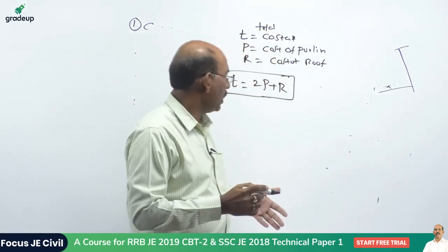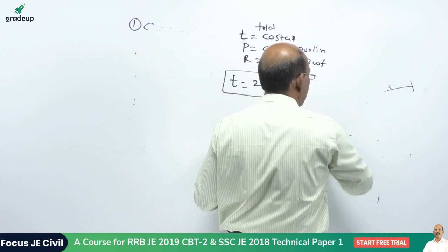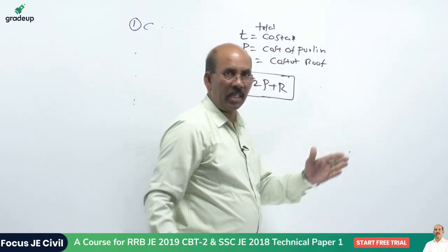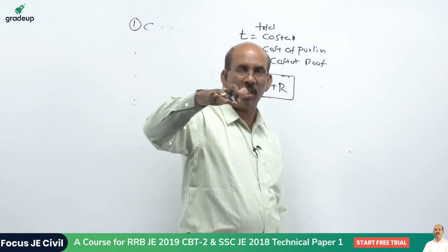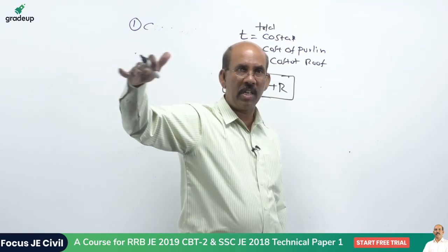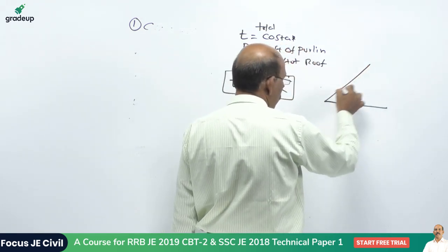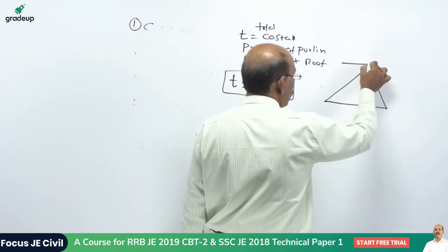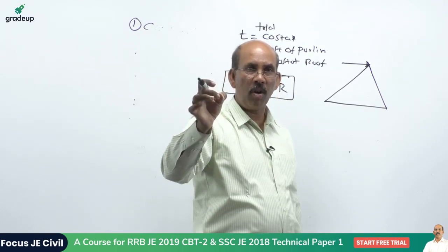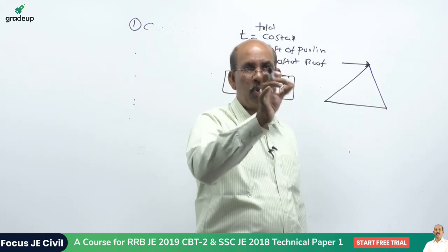The wind load is a horizontal load, especially at a higher level, more than 5 floors, where the wind load effect is very, very high. In that situation, the loads are horizontal loads. According to the IS code on wind load and seismic analysis, we have the respective equations. Please refer to the code book and use that.